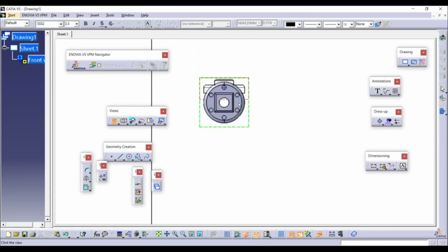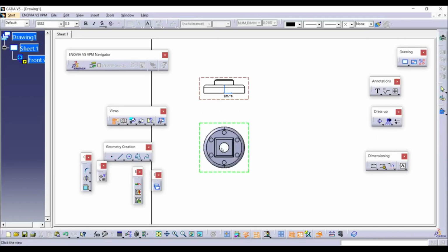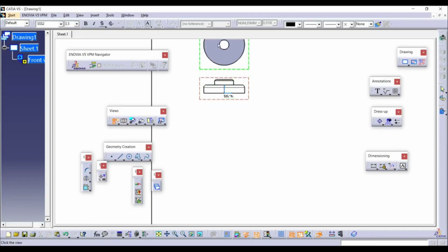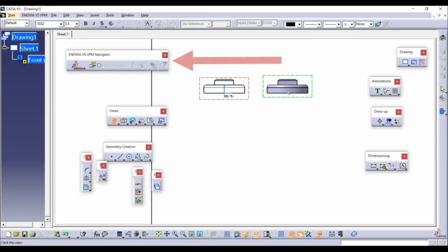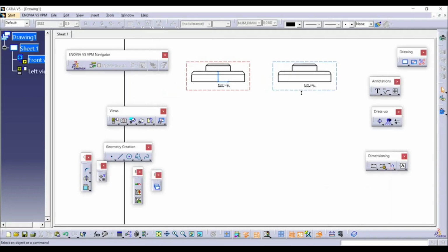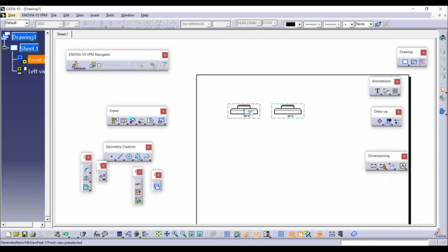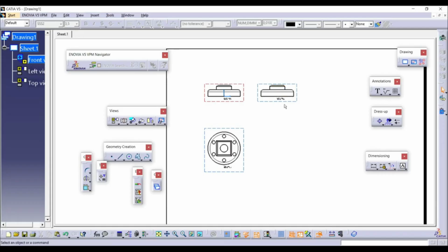And now if you go with a mouse here, you can see if you go down from this view here, we have a top view here. If we go up, we have a bottom view. If we go to the right, we have a left view. If we go to the left, we have a right view. So this right view we get if you look from this position here in this direction, like this. Let's create here left view, this one here, and we can see this is left view. And this is the same view as the front view. Now let's select your projection view again. Let's go down, and this is our top view, as you can see. Now we don't need this left view, so we can click on this view, double click, right click. Let's go here with delete.